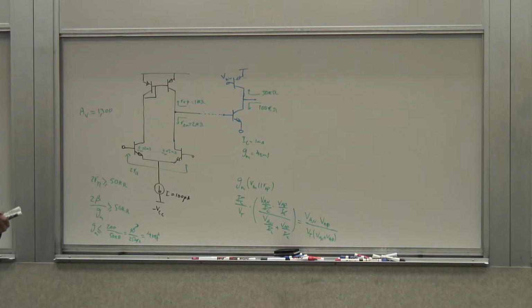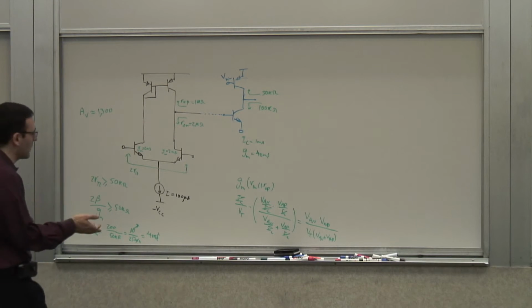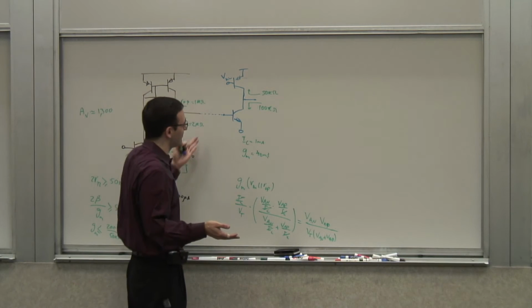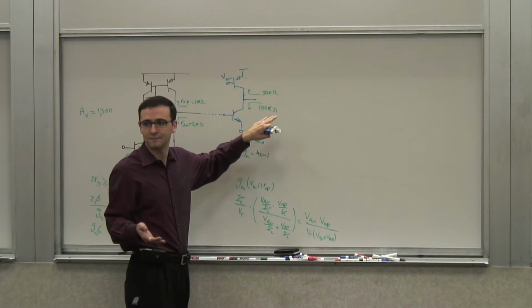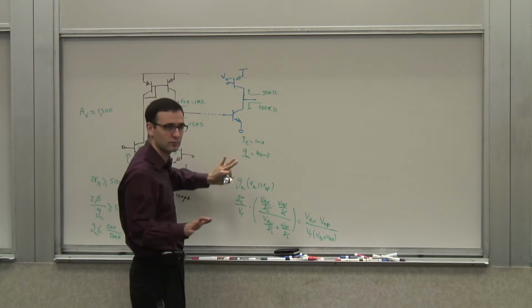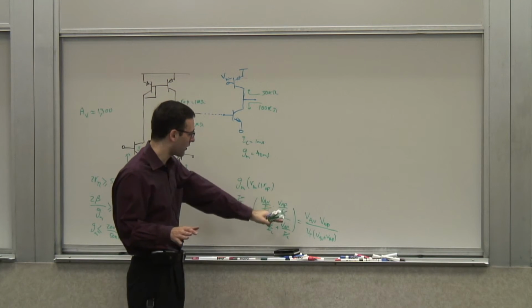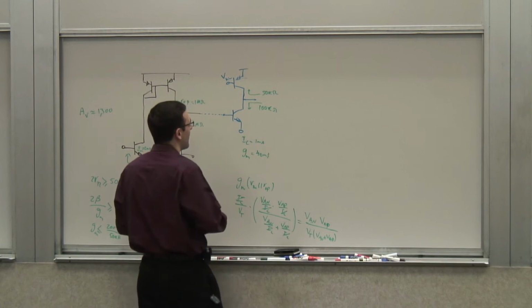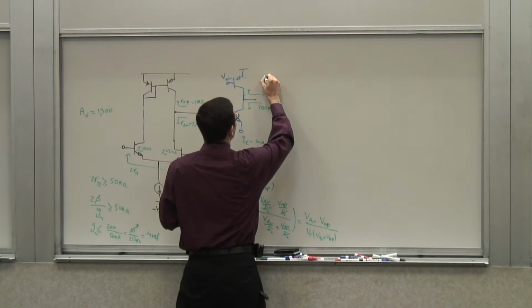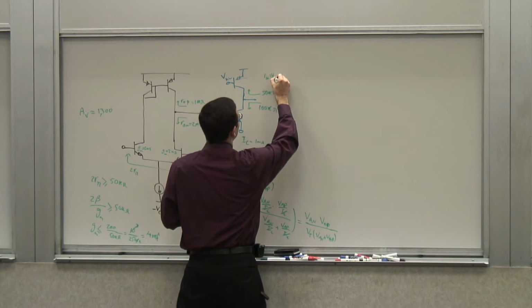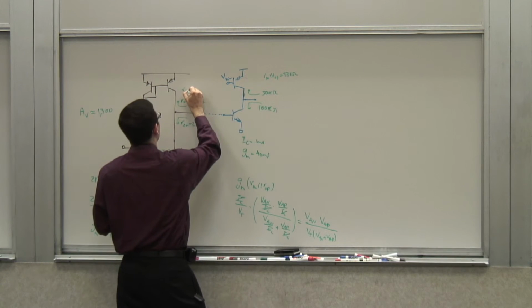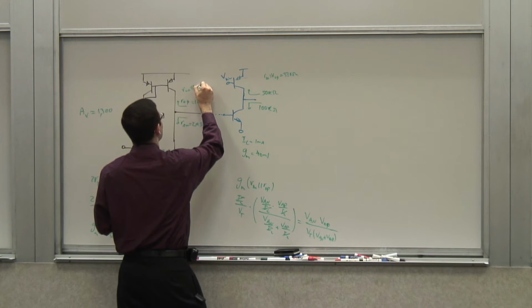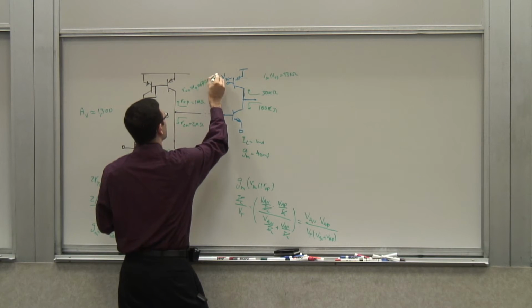Right, so as a voltage gain should be. What we see is that, if that were my only circuit, if it weren't loaded or affected by anything else, that product would be something like that. And the parallel combination of these two, basically RON in parallel with ROP, is going to be about 33 kilo ohms. And here, RON in parallel with ROP is about 660 or 670, let's say, kilo ohms.